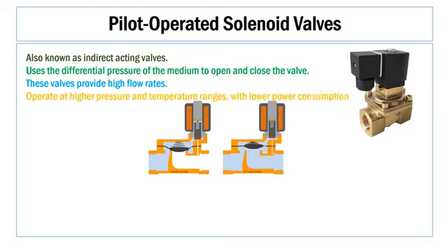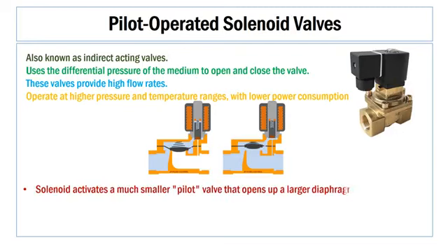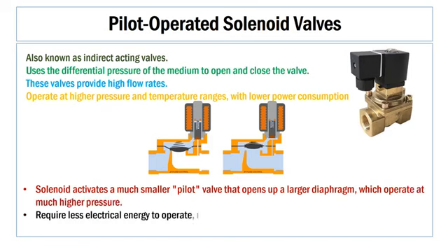In pilot operated valves, the solenoid activates a much smaller pilot that opens a larger diaphragm, which operates at much higher pressure. The pilot operated valves require less electrical energy to operate and do not need to maintain full power to remain open.